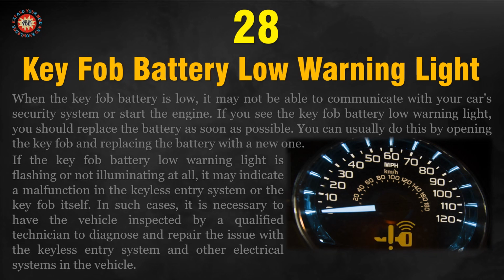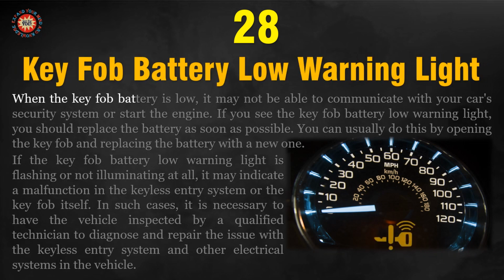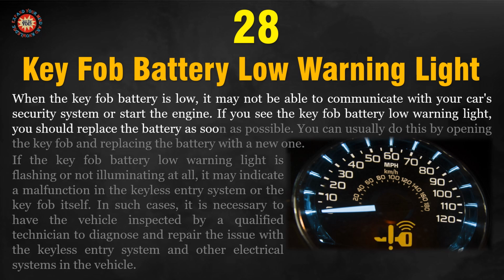Symbol 28. Key fob battery low warning light. When the key fob battery is low, it may not be able to communicate with your car's security system or start the engine. If you see the key fob battery low warning light, you should replace the battery as soon as possible. You can usually do this by opening the key fob and replacing the battery with a new one.